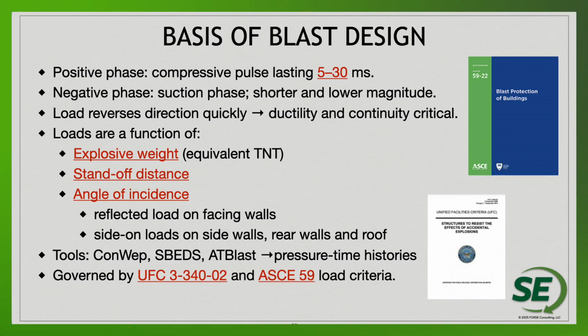So the pressure time histories are typically generated by the owner or the security authority. They use very specialized tools, which can be one of the following, like ConWep, SBEDS, or ATB Blast. So they use these to define the required input for the design. But the design engineer does not need to run the actual software or tool to define the load. So we usually use this input from the owner or the governing agency to continue further with the design for blast.